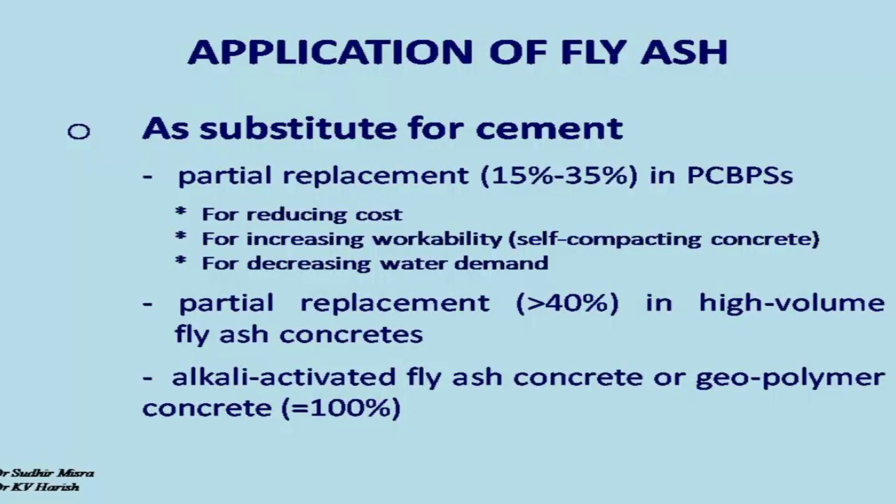Geopolymerization is a totally different process, where fly ash reacts with activators such as sodium hydroxide or sodium silicate, and in any case we are not getting into that, but it is important to know that alkali activated fly ash concretes are getting popular primarily because 100% of cement can be completely replaced by fly ash. The only thing that you have to understand is that when you do such replacement, high quantity of activators are required.